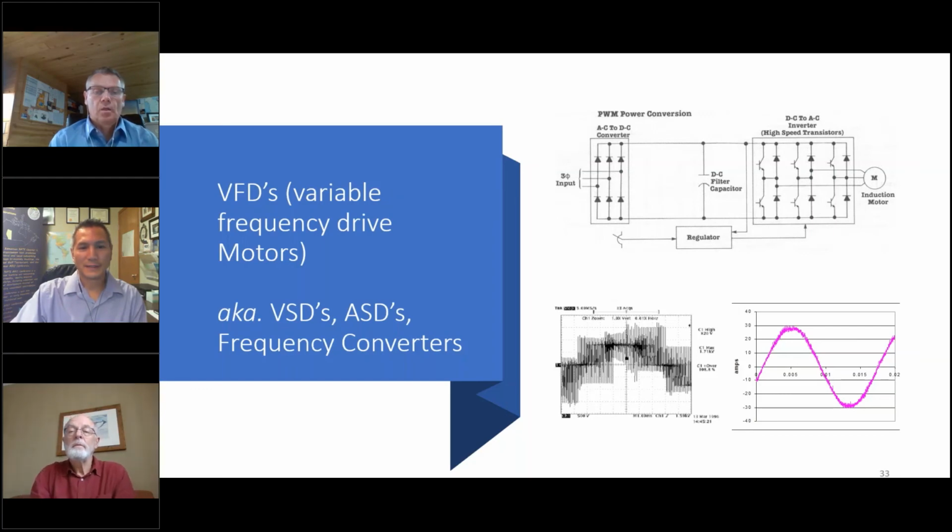Yeah, and one thing I would say is when we talked about VFD Capable and VFD Duty, the VFD Capable motor has an insulation system that's designed to handle a certain threshold of those dV/dts, and that threshold in the 575 volt world, to be precise, I think is like 1,897 volts.